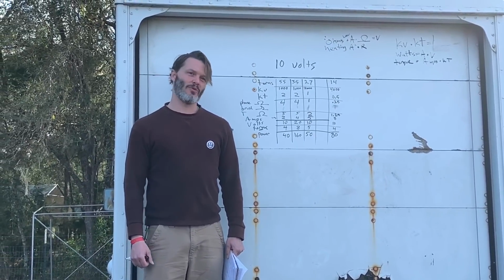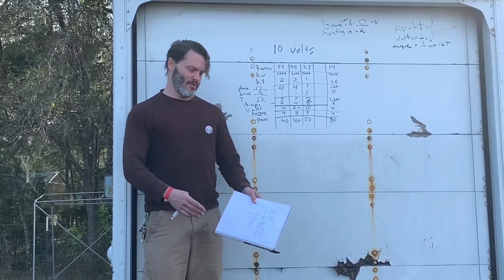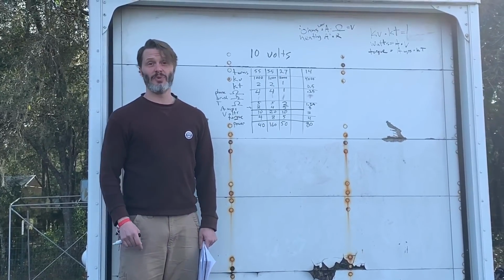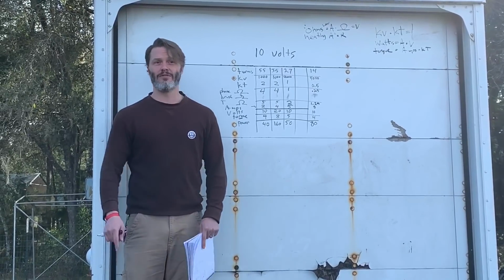And that's really what I recommend, is like the guys in your group, wheel one of their rigs. If you like the speed that it has, get the same speed motor. If you want more wheel speed, get a little bit higher kV or run a higher voltage on there.